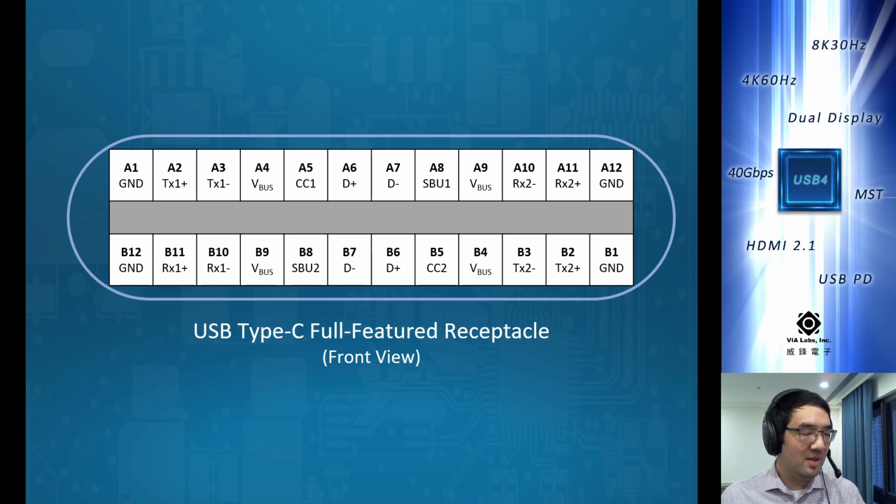The USB Type-C connector has 24 pins, and of those 24 pins, we have 4 pairs of gigabit speed capable pins. And we've highlighted those here. When used with just USB 3 SuperSpeed 5 gig or 10 gigabits per second, we are essentially only using half of the pairs of the cable. The cable orientation in this case is dictated by the CC pins. So with CC1, we're using one side. And if we flip the cable, CC2 designates the orientation, so we end up using the other side.